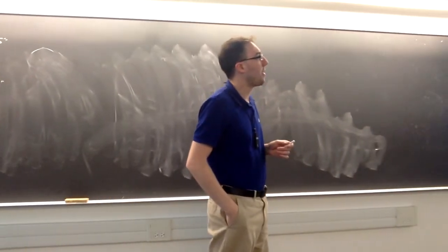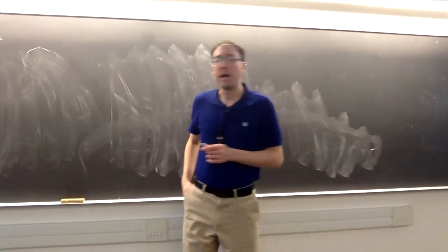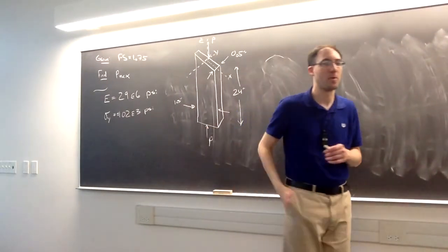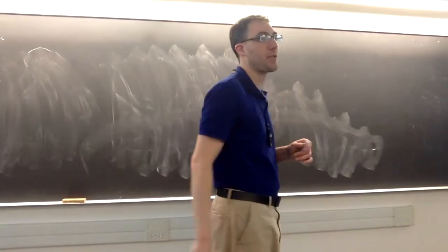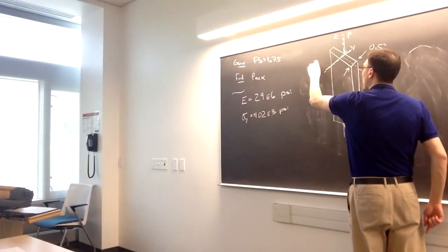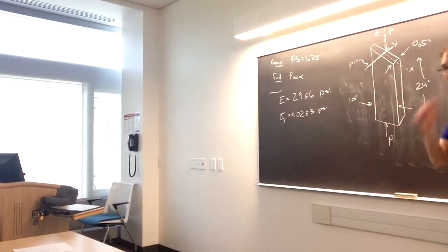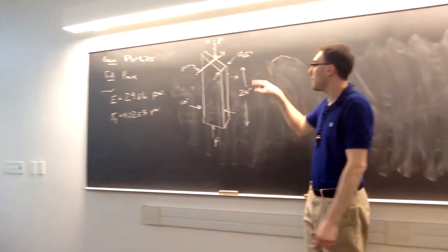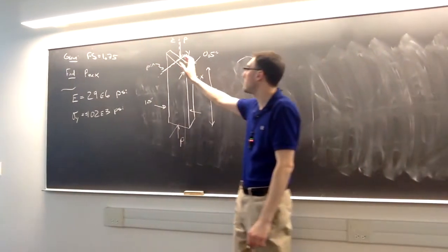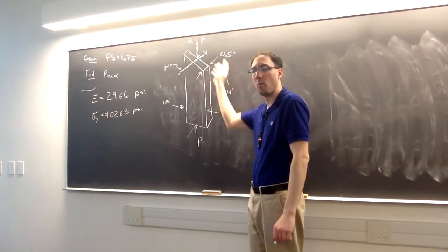So based on how this picture is, along which axis does the pin go through, the x-axis or the y-axis? The pin is going through along the y-axis. So just for our diagram, this is our pin. So when it's bending around the y, it's going to be a pin-pin direction. It is allowed to freely rotate around the y-axis.